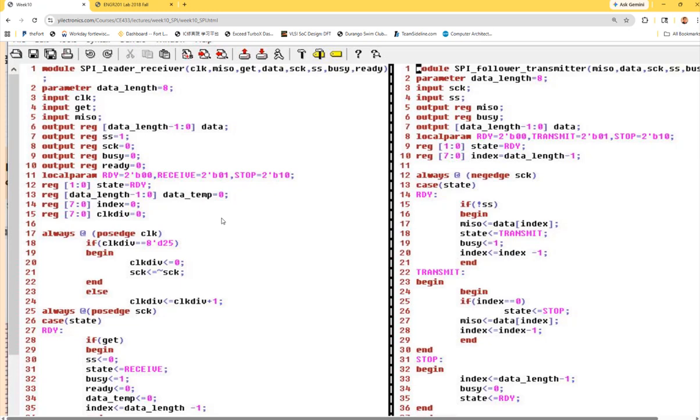And that's actually the sensor module I just gave to you. Did you see that sensor module? Okay, everyone should have a sensor module. It's a light sensor, and that has a SPI module in it. So the light sensor is a photodiode. So take a look at the pinout over there. What you have, CS. Okay, CS is the chip select. It's active low. And you have a not connect, so you don't have to connect anything to it. And SDO is the data out. Data out, right? It's the MISO, okay?